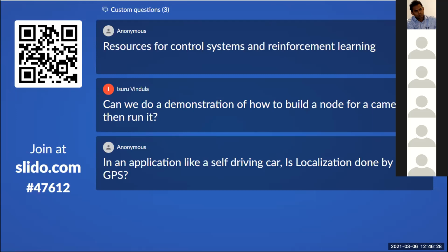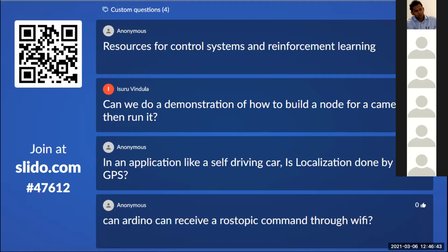I can add something to that. We are actually doing a project on the localization of a self-driving car. First of all, you can understand the gravity of that problem. Estimating the exact location to a centimeter level is very difficult, because if we are driving a car autonomously, we need that precise vehicle localization. Of course, we will use GPS, but GPS can jump here and there, and it is not centimeter level accurate. There are centimeter level accurate GPSs, but they are very expensive.